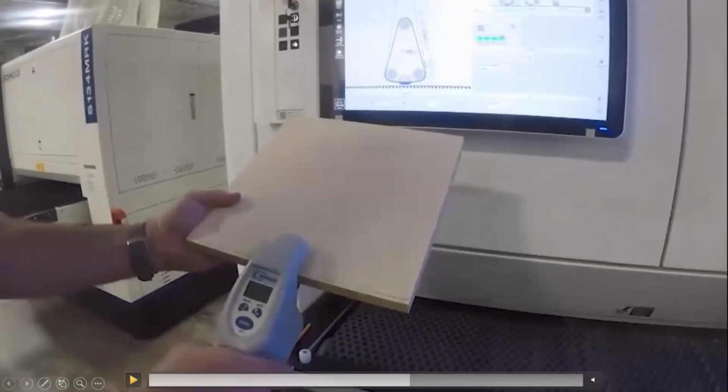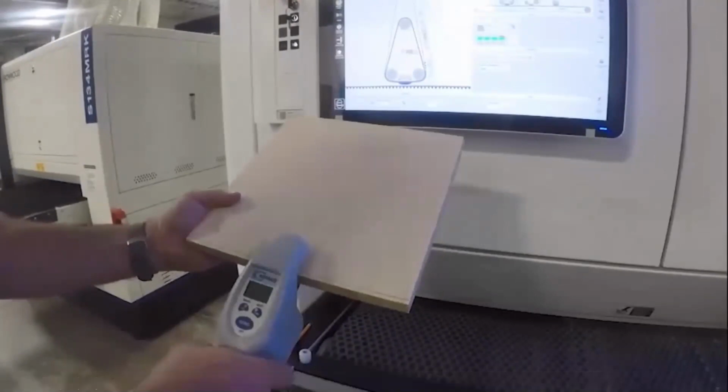One nice thing about magnetic segmented pads is I do have plus or minus 1 millimeter of float in my pads. So even if my thickness isn't exactly right, I will still sand that workpiece exactly the same as I would if it was entered correctly. And of course, we all know that there's variation in panel products. So obviously we want to be able to accommodate and float on the surface, even if we have some variation in one batch of boards to the other.